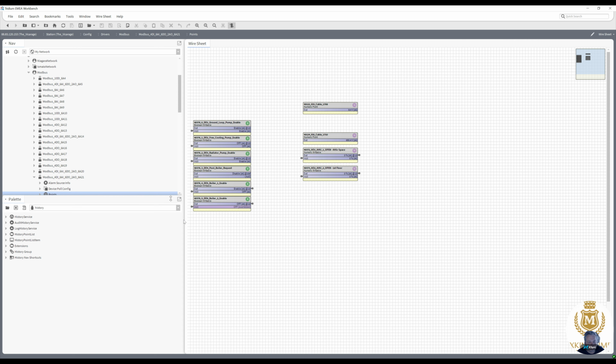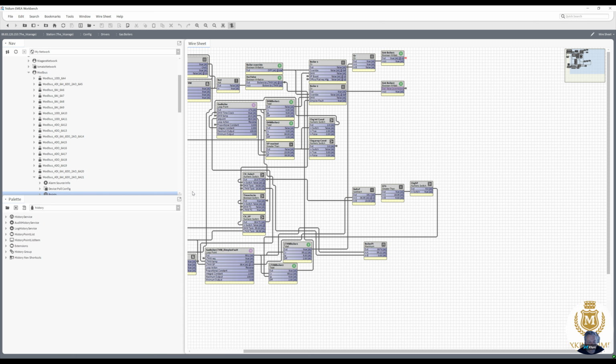He's overridden gas boiler 2 to off. But there's gas boiler 1 going on and off. So let's just double click that point and see where it takes us. True. So it's that one that's doing it there. That control variable is doing it there, and that's coming from LTHW required there.